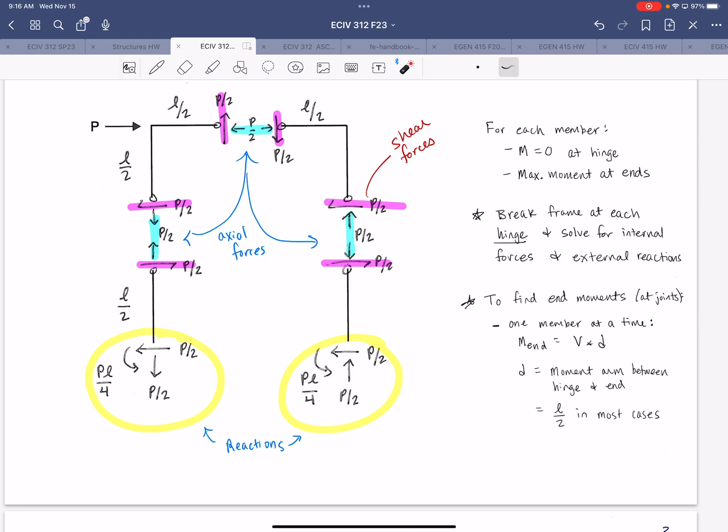Yeah. So when you calculate the moment at a rigid joint, do you just look at one side of the frame, not the top end and the downward member, like the L shape, or is it just one member? So what you'll find is if we were to do that for this frame, we would want to know the end moments of the beam, right? So in order to do that, since we're assuming that the hinge is located in the center, we only need to take one side of that, right?